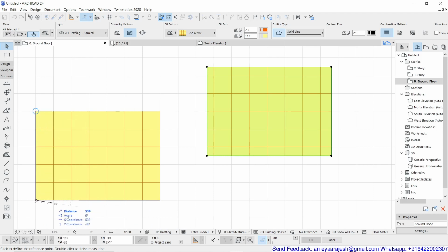So with intervals of 600, everything was getting exactly occupied. In the copy, the distance is the same, and you can see the spacing of the grid line has not changed, but overall the pattern is not exactly fulfilling the full tiles. Instead, there are a lot of cut tiles. All this is happening just because of one setting, which I'm now going to explain.